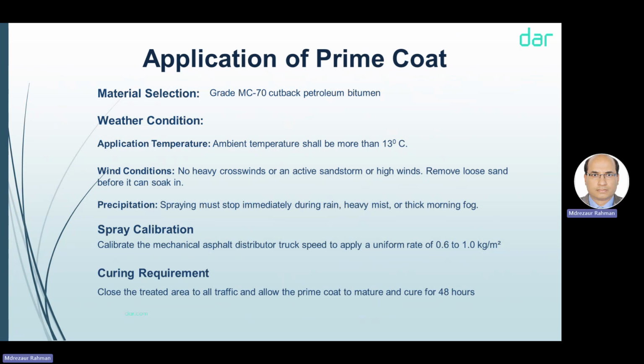This is spray calibration, the spray rate. So for the prime coat calibration, we have to check the distributor truck to make sure it gives a uniform rate. Calibration is actually the rate of spray. Exactly.